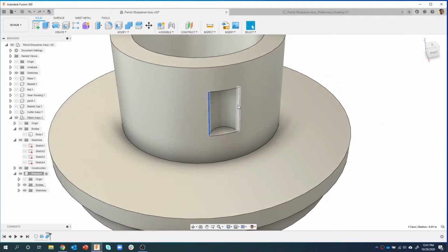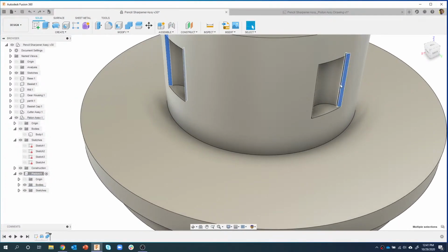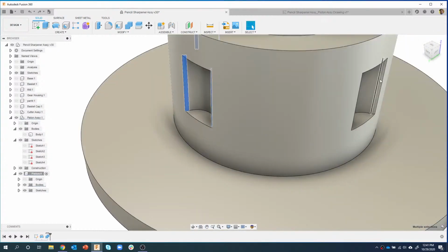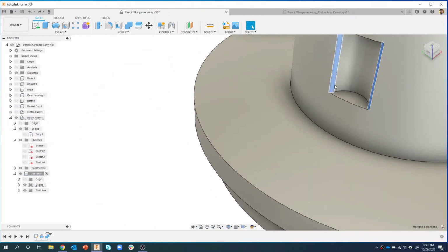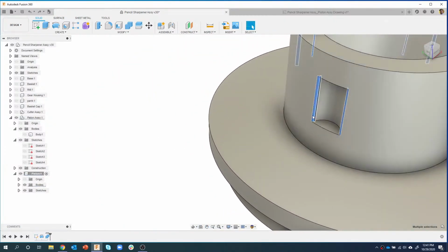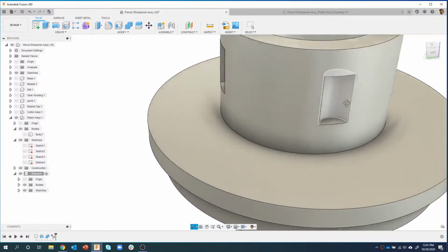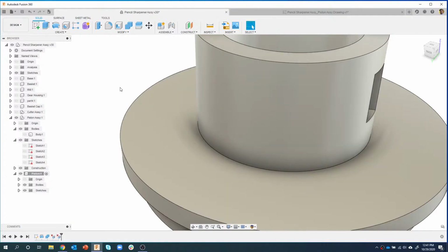So the first thing I'm going to do is get rid of these fillets because I want them to be true fillets when we're all said and done. So I'm going to select these faces, oops, and rotate around, grab that, and I'm just going to say delete on my keyboard, or I can right mouse click and say delete, and you'll see that we've now removed those fillets off of there. So the next thing I would try is deleting this face again, but I get the same result, which is kind of weird. Okay, so I can't use direct modeling.